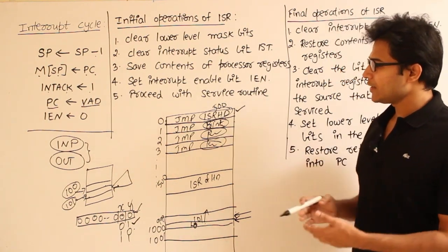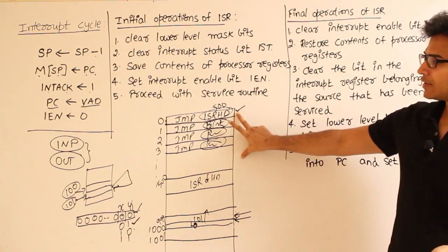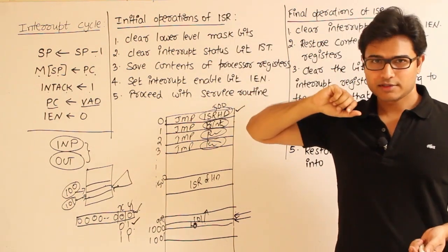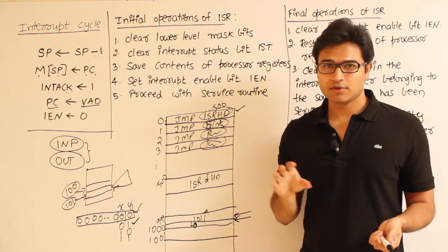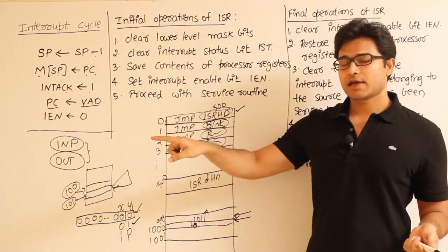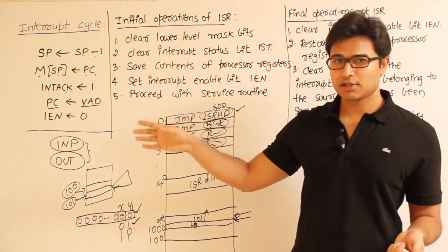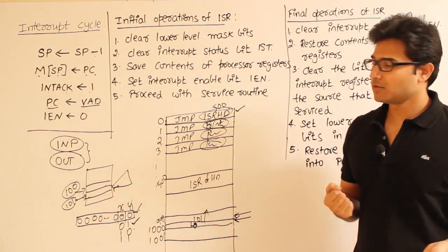So like that, if you have, let's say, 8 devices, then the first 8 locations will be filled with that. Then the encoder is supposed to give you 3 bits. Got it? If you have 8 devices, see, in case we had discussed the example with 4 devices, that is why we have an encoder which is having 4 inputs and 2 outputs. In case you had 8 devices, then your encoder will be having 8 inputs and 3 outputs. Got it? That priority encoder.